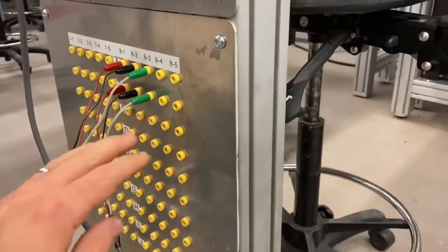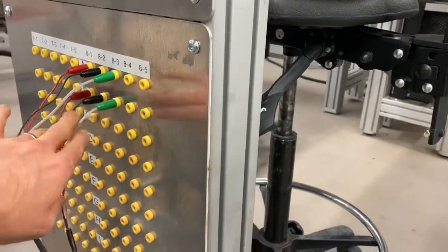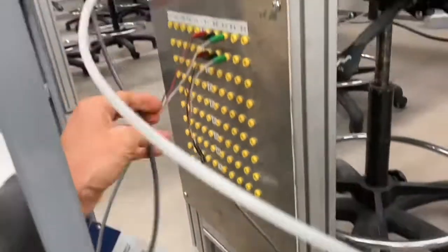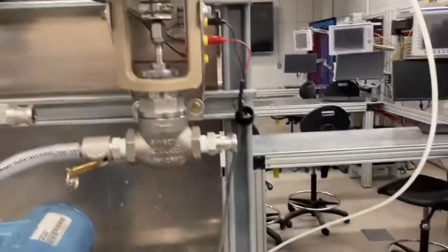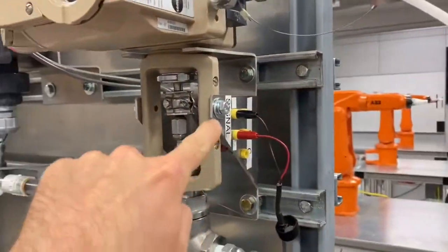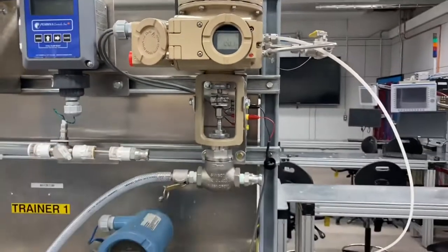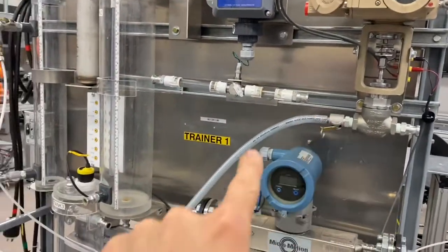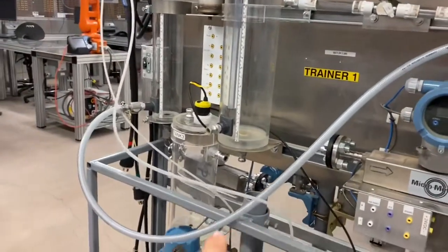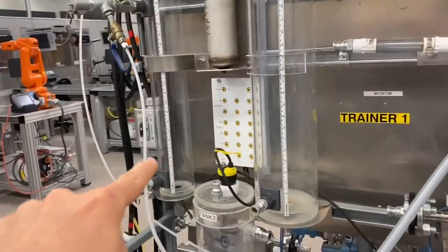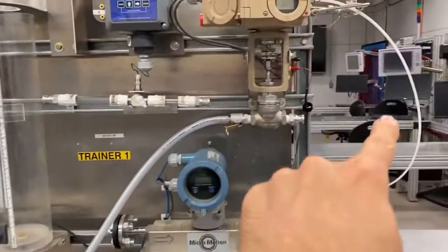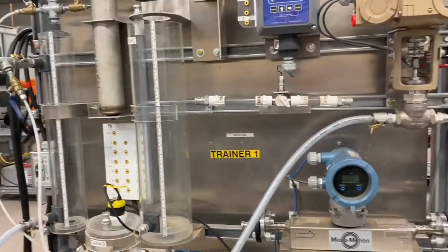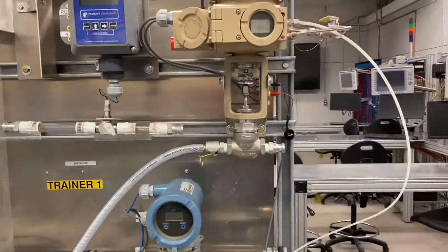If we go on to the end of our bench here, you can see these 3 wires right here. They flow down on this line right here, this wiring, up to our control valve right here. It's connected to our control valve. So our control valve is venting to atmosphere. It is controlling the pressure in this vessel. It's controlling a back pressure. So when the valve opens, it relieves pressure and the pressure drops in the vessel. So that's what we're using to control.